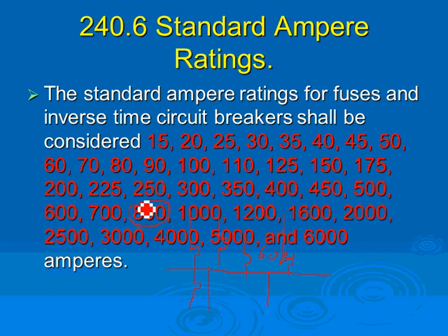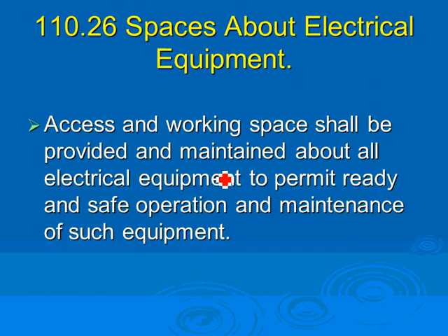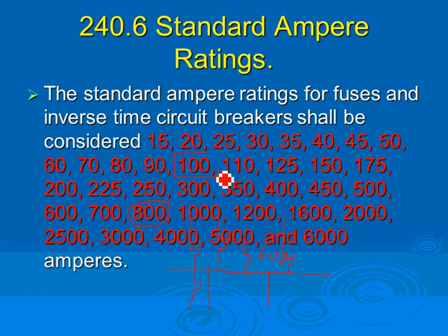But generally speaking, starting from the 100 and up, any one of these, if it's an adjustable circuit breaker, can be adjusted in increments of 0.1 up to 1. If that makes sense. So yeah, the limit becomes so many settings that you can have. Am I the only one who's excited again here, that there are so many circuit breakers?